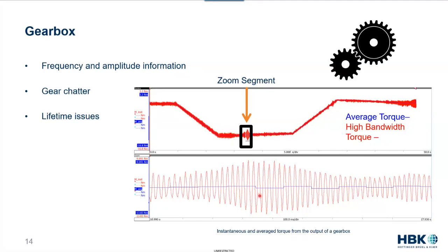If all we can view is the filtered value, that average value, rather than the actual torque ripple, we're just not going to have visibility to those high torque swings that are happening in the system, which can affect how well our system operates the way we expect.